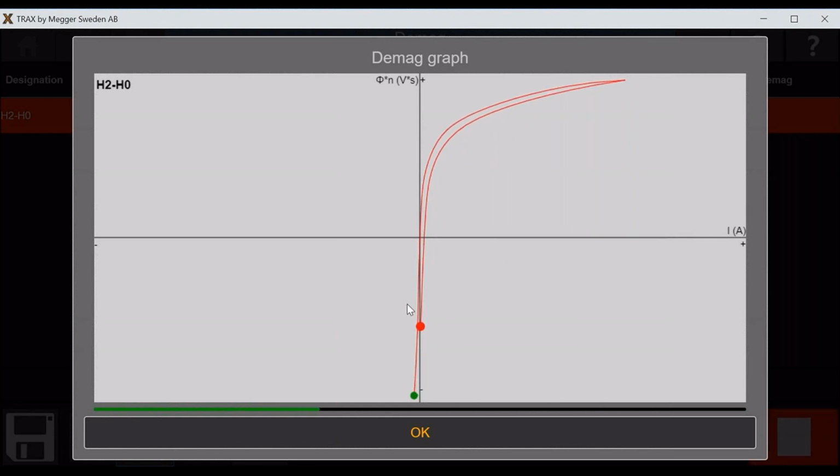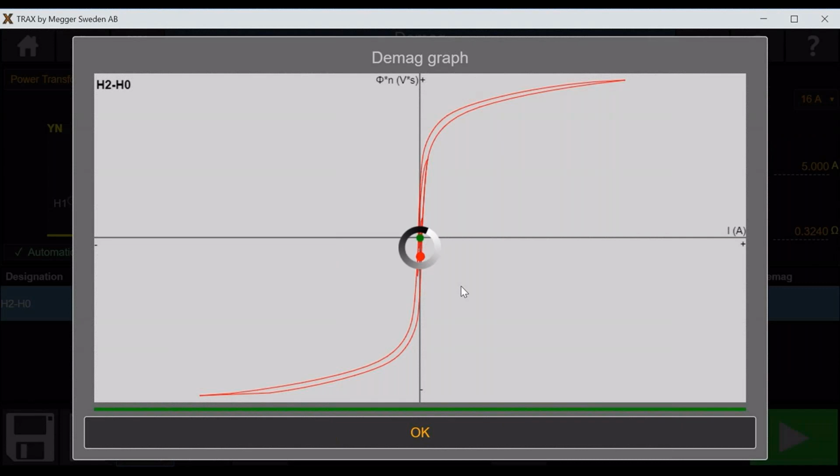Once the maxima is reached, now we're looking for the minima. We get to the negative point, and now we just go back and we start drawing the hysteresis of my transformer. By doing this process continuously and changing the magnitude of the current that is being applied, we can locate exactly the point of zero remanence, zero coercivity, and that's where the process finishes.